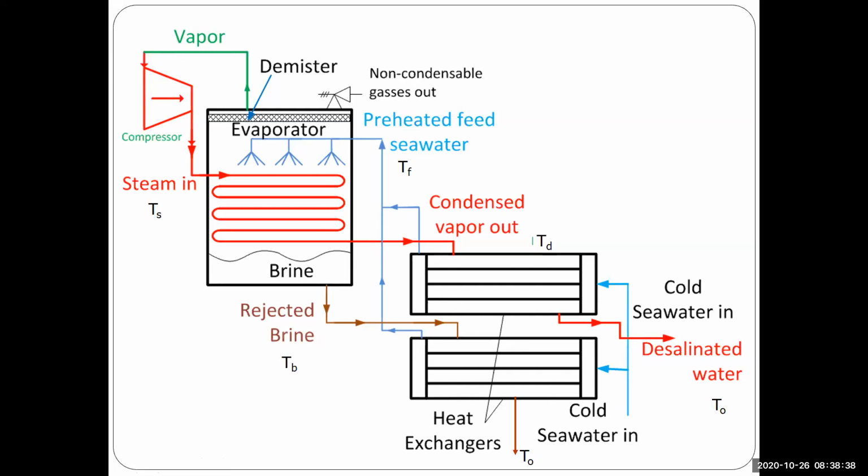What we wanted to look at then, after we talked about that these units are throughout the world, they are not very common as the units which use thermal vapor compressors, but they have a good feature, that they are standalone units. You don't need to connect them to a boiler. All you need is a source of mechanical power to run the compressor, which can be an engine, a diesel engine, for example.